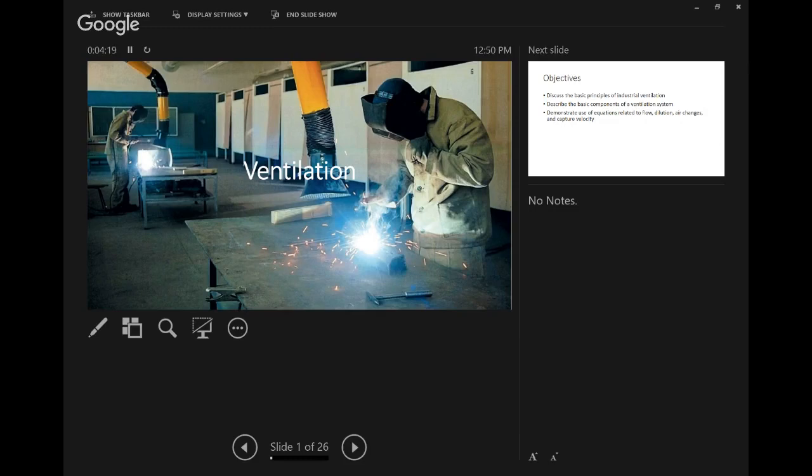He just tore off a little shred of paper, and then he was holding it near the hoods, ventilation hoods, now the systems didn't look like this, just to see, is it actually getting sucked in or not? And, I mean, there are some things to look for. You don't have to have tons of fancy equipment to know that it's not working or to know that it is working. It's kind of in between where it's hard to know, but if it's not working at all or just very poorly, then you can usually tell. And if it is working well, you can usually tell.